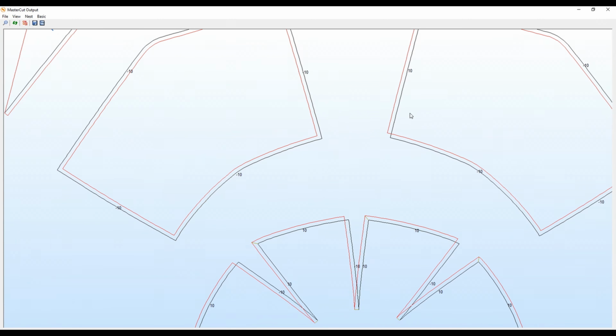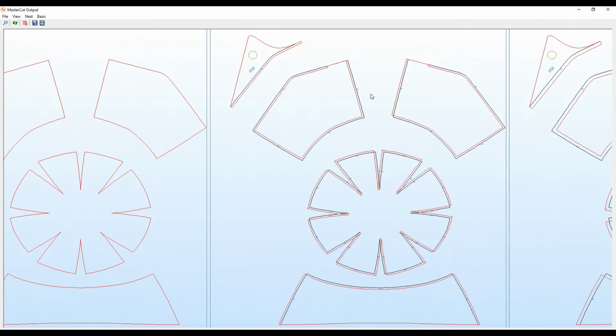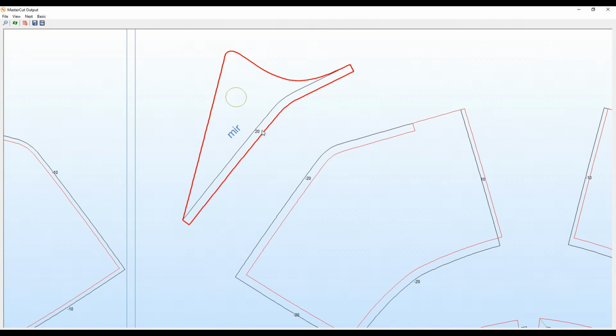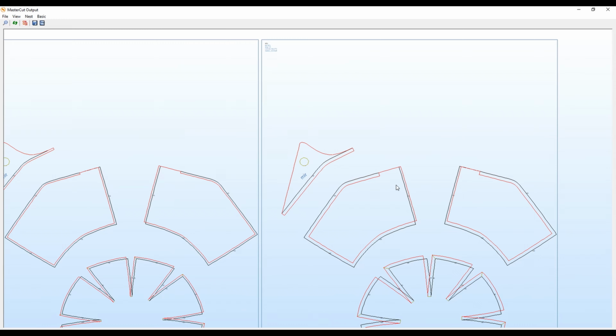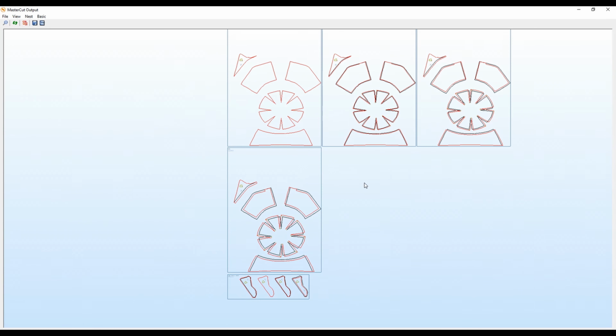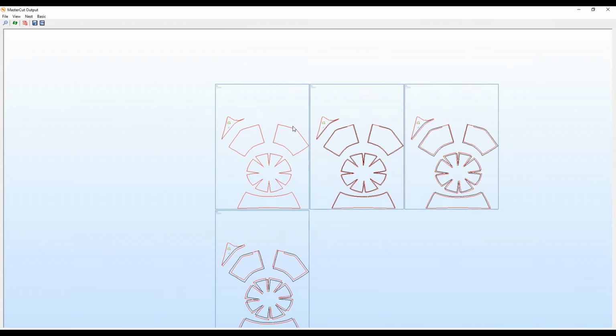And you see what happened here. It's fine. Since we are using an offset of 10, the next numbers here on the third step should be 20 and minus 20. And you see it works fine. So here you can check whether you have all the offsets right. Now the orientation, this is now a 0 and 90-degree orientation. The 45-degree and everything, this will be shown to you in what we are going to do next. And this is the nested output.